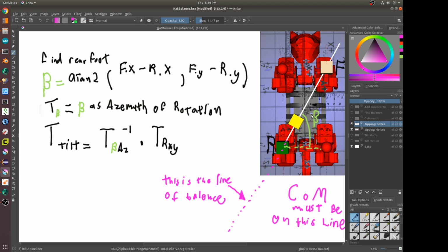So in order to do that in code, we're going to need a couple things. So the first thing we need is this beta value. Now beta represents the angle between our tipping line and the robot fiducial's y vector. So the reason we care about the y is because we know we're going to tip from our sensor is aligned with that y vector.